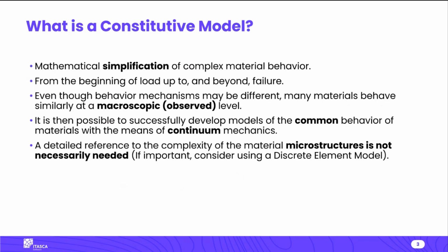So when you zone the model, you need to assign a constitutive model. This is the same as any continuum program. What you have is essentially small continuum models inside of each block. A constitutive model is just a mathematical simplification of complex material behavior, from the beginning of load up to and beyond failure.